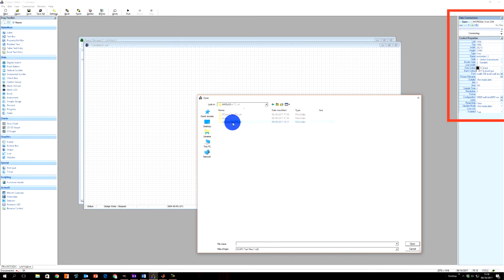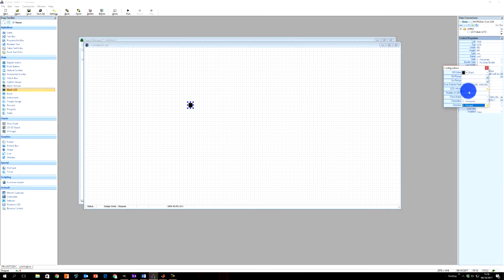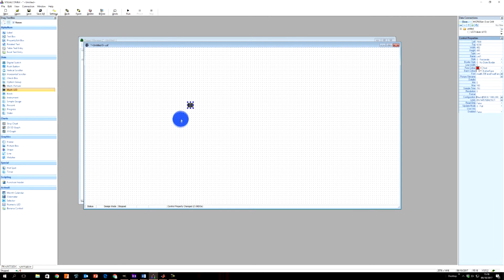Now in the Connections window, you'll be able to see the LED parameters and signal blocks from the model, which will be our connections. Now we can start creating the interface itself. From the connections, you can see our LED parameter we made earlier. We'll drag in a multi-LED control and configure this to represent the 10 LEDs on the front of the MICROGen. We'll tell it that there are 10 LEDs and then link the LED value parameter we made earlier.